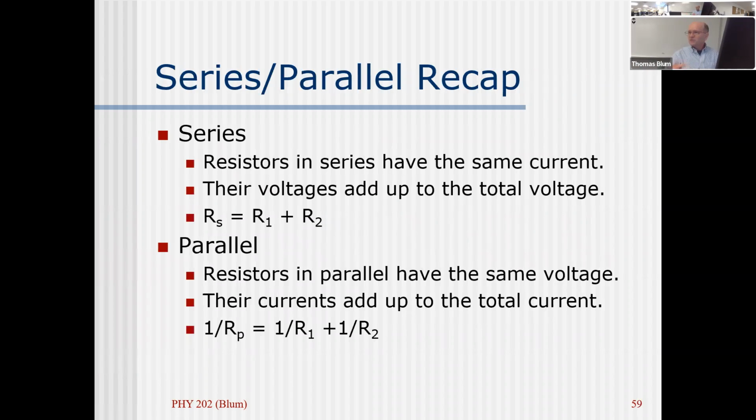So we have series, we have parallel. If the resistors are in series, they see the same current, their voltages add up and the resistances add up. In parallel, the parallel resistors see the same voltage. It's their currents that add up, and the equivalent resistances add reciprocally.